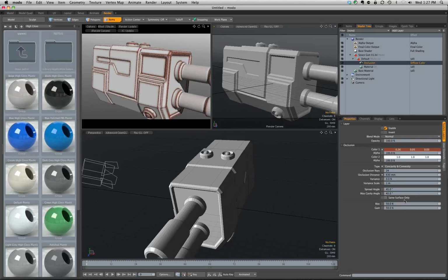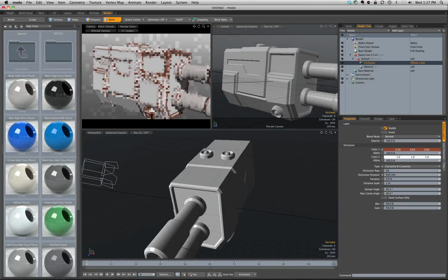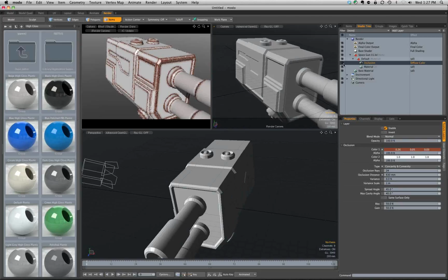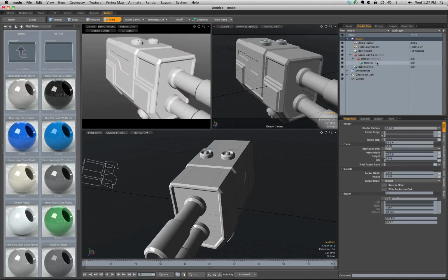Okay, and you can take this a lot farther by baking and using UV maps, and I don't have enough time to do that. I'm looking at the clock, but Brad's got a tutorial up on the forum, not even a tutorial, just a demo video. I'll show you how to actually render this and bake it in. You can just right click and say bake to file, and then jump over to the paint tab and paint right through it. But this is a really great way to work, especially when you want to just create some dirty edges. And in one of the tutorials in our 501 course, we just make some keys, and one of them's clean and pretty, and the other one is just all kind of dirty and grungy like it's been used, which is pretty nice.